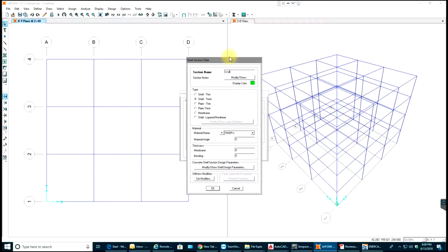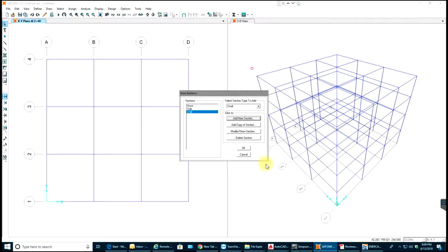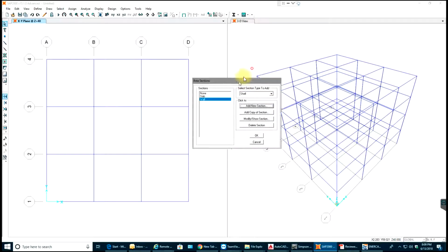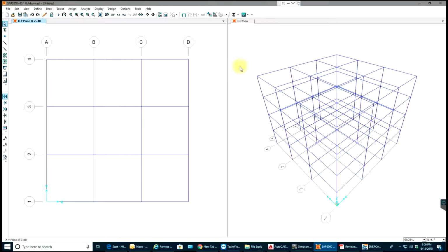I mentioned it in the next video tutorial. Again, in the next video tutorial, while doing the wind load analysis for frames, in Y direction, instead of selecting frames, I selected rigid diaphragm, so that didn't give me proper results, so I had to rectify it. So yeah, just make sure that you are giving right information all the time.